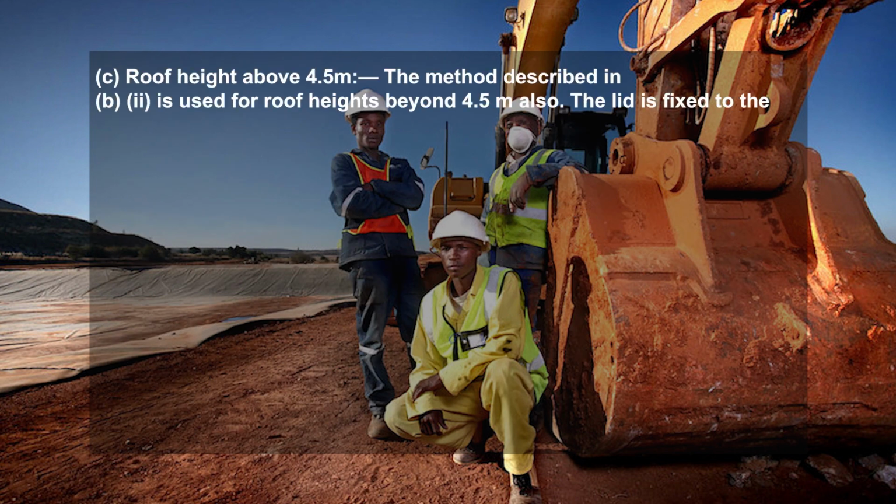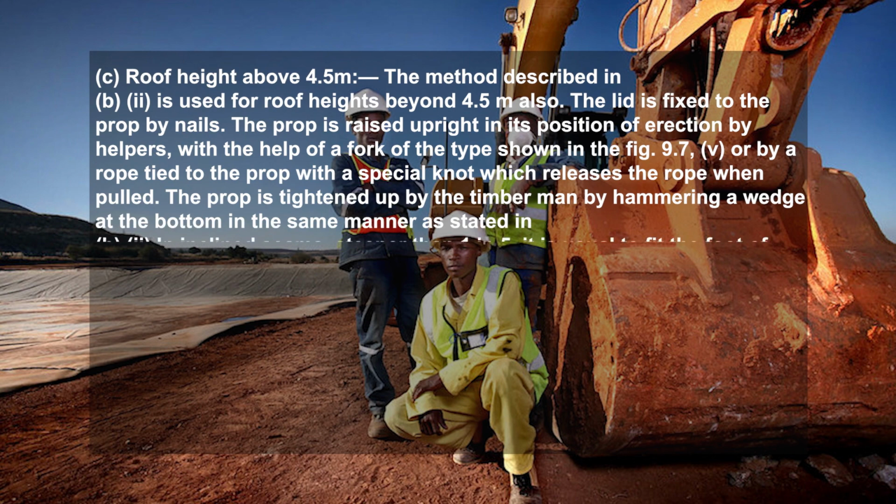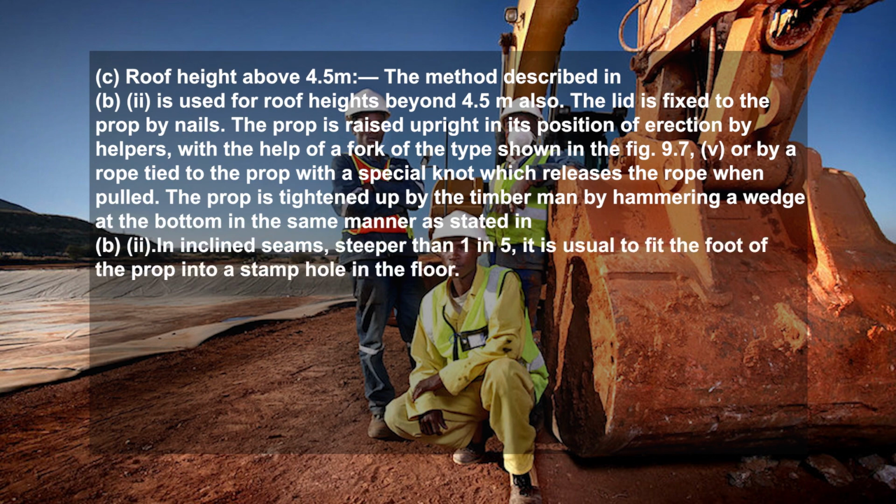Next, roof height above 4.5 meter. The method is used for roof heights beyond 4.5 meter also. The lid is fixed to the prop by nail. The prop is raised upright in the position of erection by helpers with the help of a fork, or by a rope tied to the prop with a special knot which releases the rope when pulled.